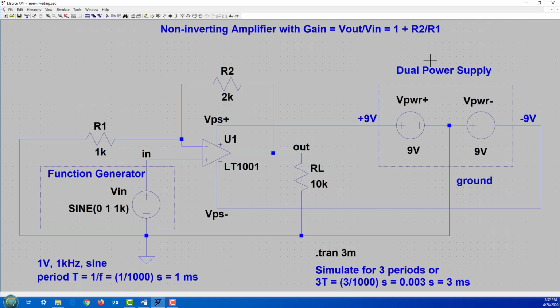And the reason I put function generator is because if we were building this in the lab, you would replace that with our function generator on the benchtop. Similarly, on the right side, I show you plus minus 9 volts. If you look back at the lectures, I told you why we pick it that way, and the middle point is ground, if you notice. So in the lab, you would set this up using the dual DC power supply, and so on. That's why they're marked that way, just to let you know that this is actually just one step away from the benchtop work, okay?